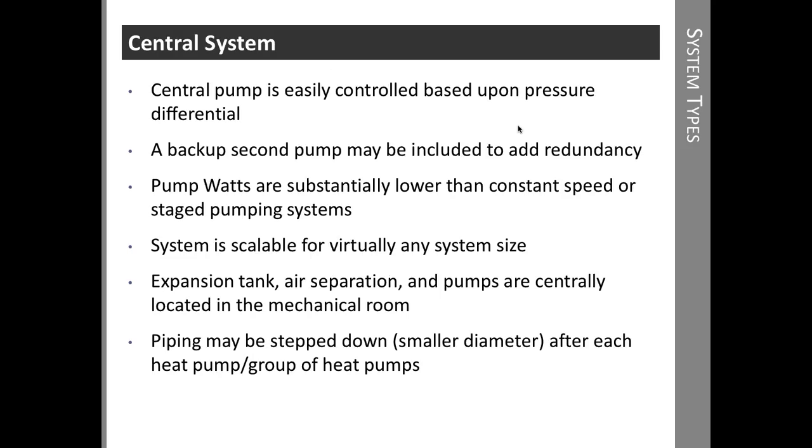All right, so it's pretty easy to control. There really isn't any wiring from the pump, other than a start-stop function. But as far as controlling flow rate, it's simply based on pressure differential. So as the heat pumps are running, the valves are opening. And if redundancy is an issue, the newer pumps like the Grundfos Magna 3 can easily be used with a second backup pump. In fact, they talk wirelessly. So if one pump fails, the other one takes over automatically.